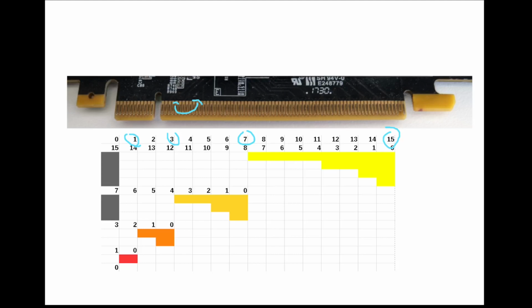Instead of rerouting traces, we can instead turn to CPU configuration to configure the host instead of the attached device to run lane reversal, but this option is almost never available in the BIOS of a normal motherboard, including the one that I have currently shown before. However, Intel has public datasheets indicating hardware level configuration of the PCIe lanes on the platform, and we can use this to our advantage.